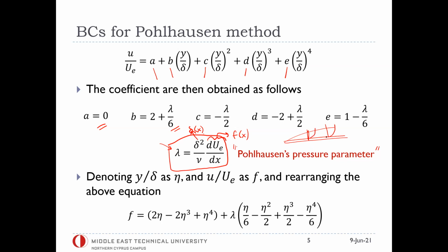Okay. So now the next question is, once I get Ue over UX again from an implicit solution, this means that this fourth order polynomial can give me realistic looking velocity profile shapes. So I satisfy my first important condition. But the second condition is, does a velocity profile like I just found actually satisfy conservation equations?